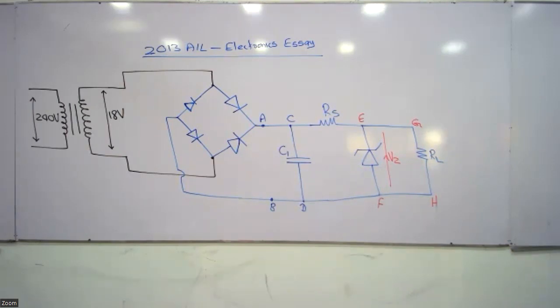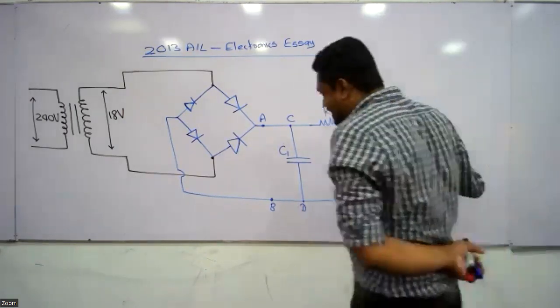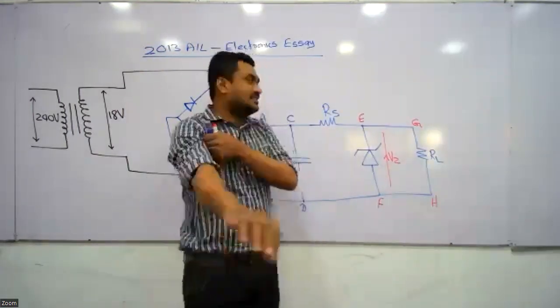We should draw the output voltages under these conditions. What are the conditions here? Roman number 1, transformer output. Roman number 2, rectifier output without the smoothing capacitor. Roman number 3, rectifier output with the smoothing capacitor. Show the capacitor connection in the circuit that you have drawn above. That's why I asked you to read the entire question before you draw this figure.